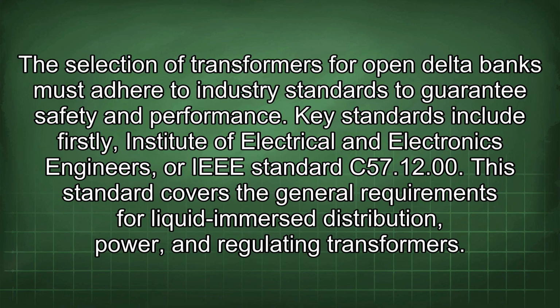The selection of transformers for open delta banks must adhere to industry standards to guarantee safety and performance. Key standards include, firstly, Institute of Electrical and Electronics Engineers, or IEEE Standard C57.12.0. This standard covers the general requirements for liquid-immersed distribution, power, and regulating transformers.